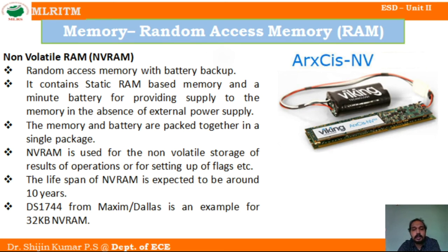An example for this NVRAM is DS1744, developed by Maxim Dallas. That is a 32 KB NVRAM. NVRAM simply means a RAM plus a battery, so that when the power is gone, the data will not be gone.